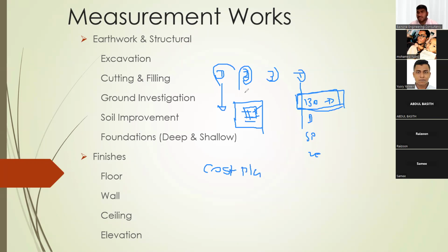This cost planner has to tell the client, at this stage, this is the cost of your building. To tell the client this, he cannot just go and look at the area and multiply. No, there is a process called elemental cost planning. That process starts from the first stage, the concept stage itself, and is done by this cost planner, who is also a QS.